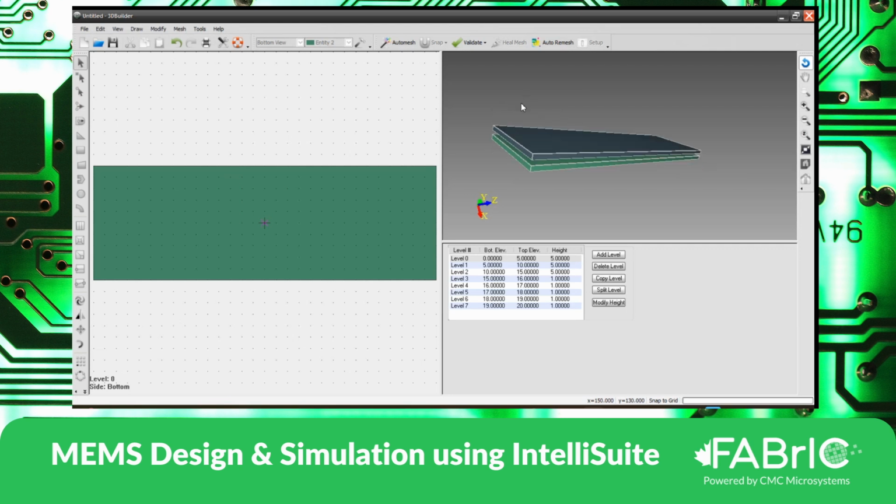Okay, let me put it this way. So you can define unique material properties, unique boundary conditions, and unique load conditions only when there is a change in entity, basically the color of the geometry. So now, if I have to do an electrostatic based simulation, then if the two beams are of the same entity, then I have a problem because I cannot give a zero potential to one and a positive potential to another because both entities are same.